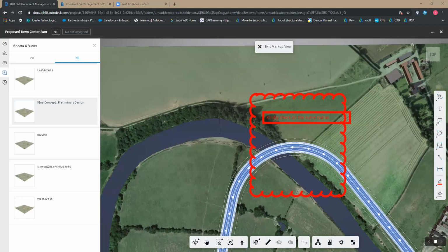Then after the watershed, you should be able to define your rainfall intensity, then define the return period, and define the coefficient of your discharge. Then from there, you can get the discharge for that particular catchment area. Then you proceed to start sizing your drainage network. So you're able to generate the sizes of the drainage network and develop the design further in Civil 3D, just as you have seen me doing for the road.